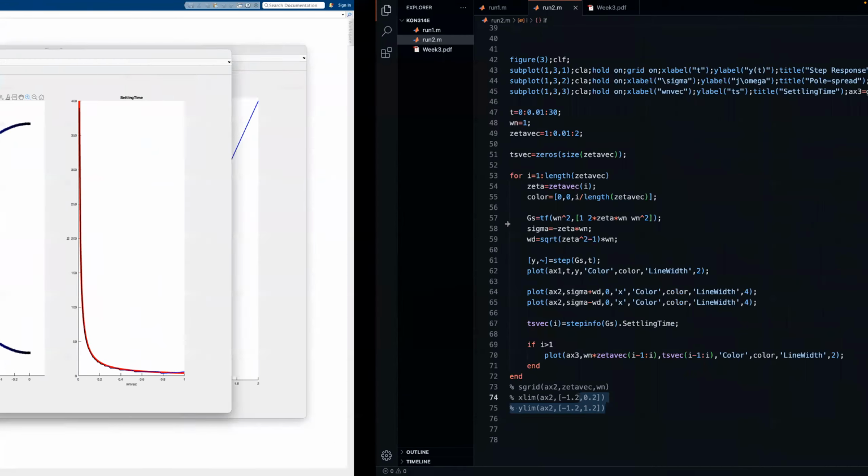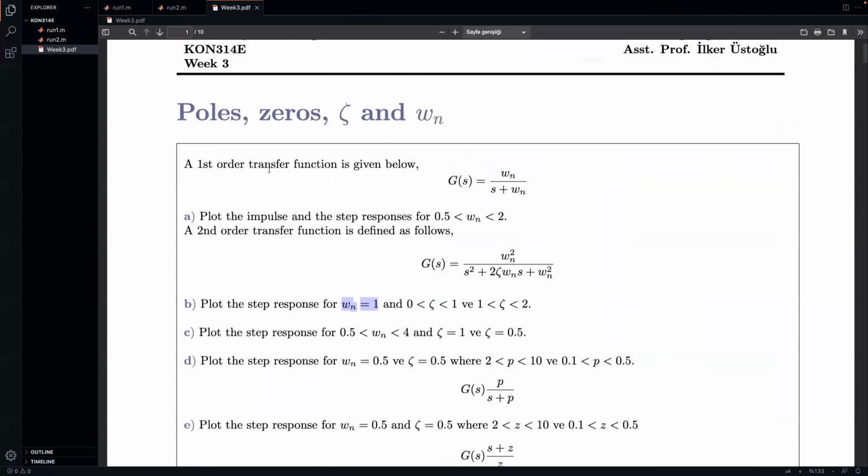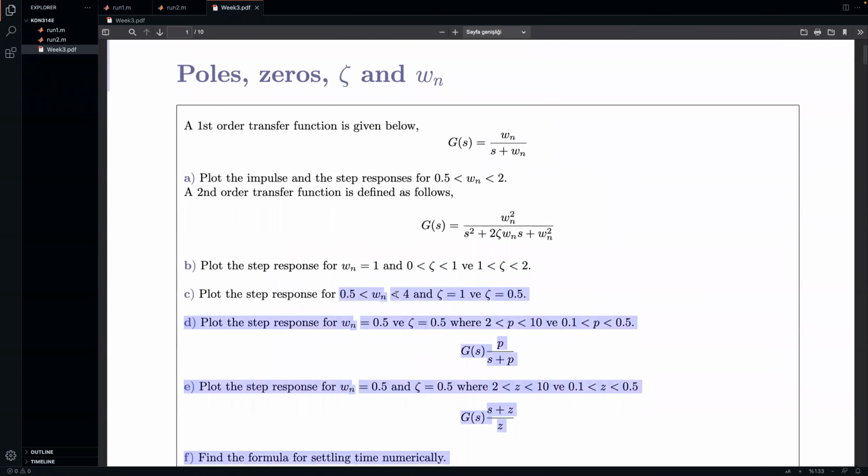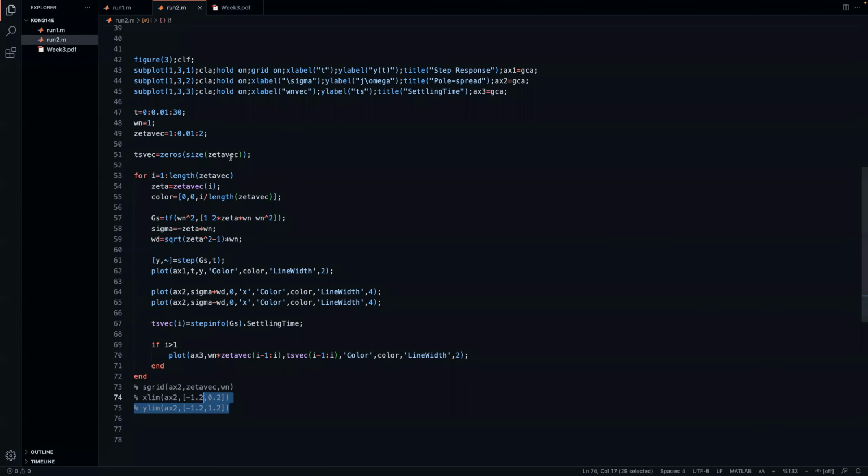Now, let's look at the second order system, but now we are going to change omega n. At this point, omega n was fixed, and we've changed the damping ratio, and we've seen that the behavior of these systems is decided by the zeta value. Now let's see what happens if we change omega n. Let's fix zeta at 1 or 0.5, and let's vary omega n and see what the result is.